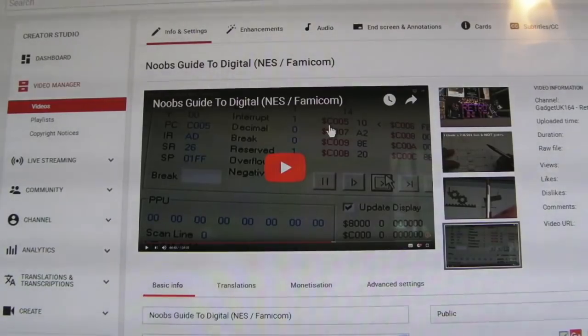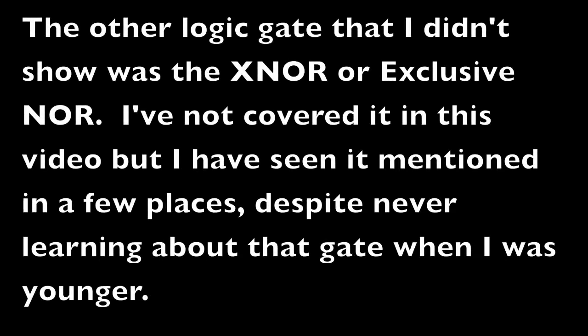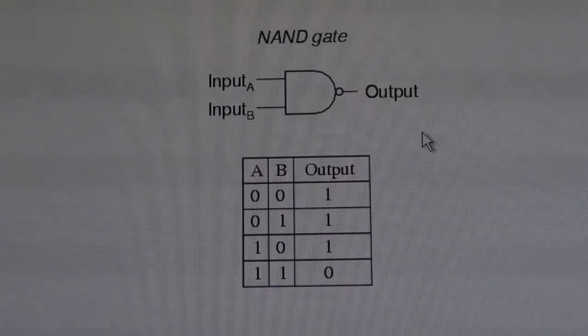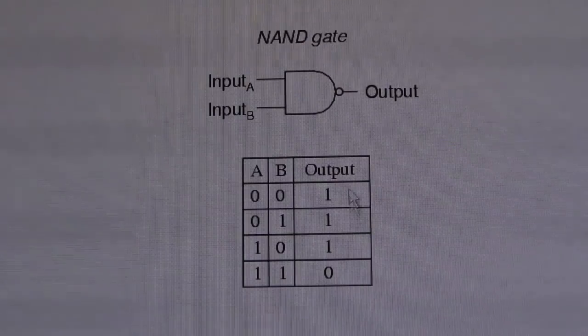Earlier in that video, when I talked about the logic, I mentioned truth tables, and I think there was a logic gate missed off there, so I'll just briefly show that. So there's a basic example of what was meant by a truth table in that video. There's your NAND gate, so you've got the inverted output, and you can see input A, input B, and you just have a column for A, a column for B, and your outputs, with each possible combination and its output. So that's the truth table.